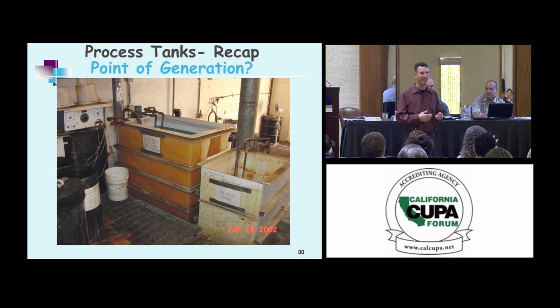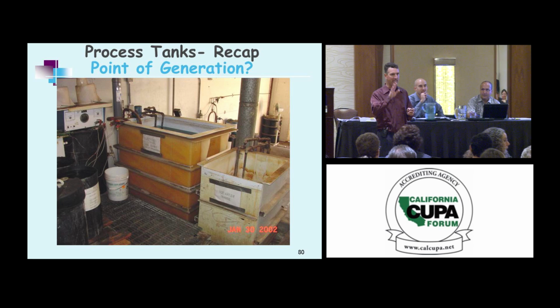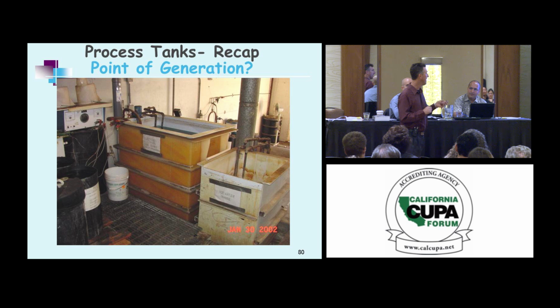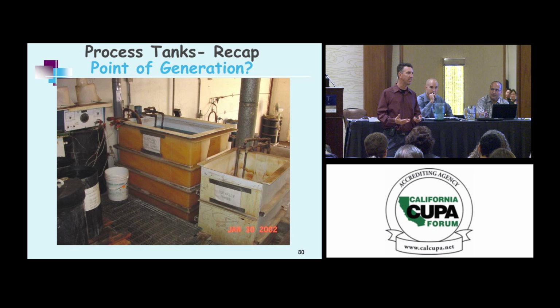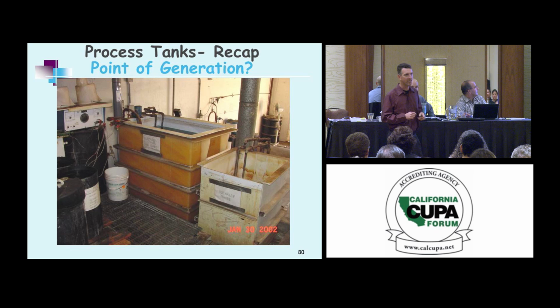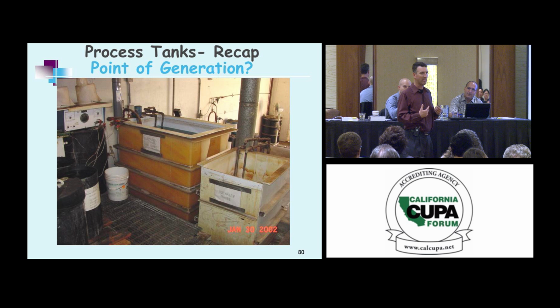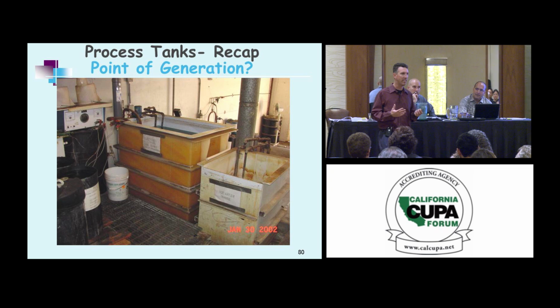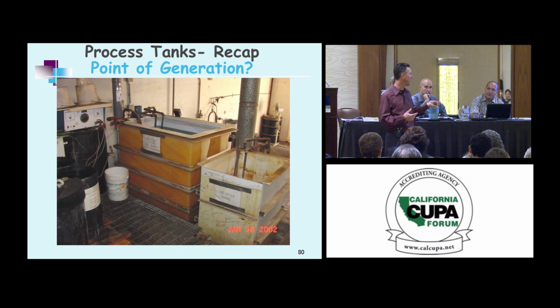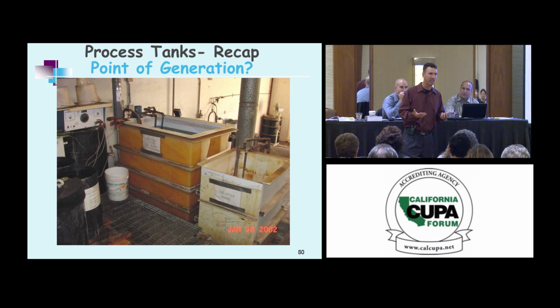Is this waste going in? Yeah, waste going in. Question. So that's a treatment unit. Right. So, yes, if that's a treatment unit. And yes, because he is changing the characteristic, the water's coming in, he's removing the water, now he's making a sludge. It is a treatment unit, but in this case, I tricked you all. Made it non-haz coming in. So it's not a regulated treatment unit under our scheme, because they took something non-hazardous, made it hazardous. Now they have to manage it. So if this is a tank, they might have to meet tank standards there. But since they treated non-hazardous waste, they wouldn't require like a tiered permit, if that's what you're asking.